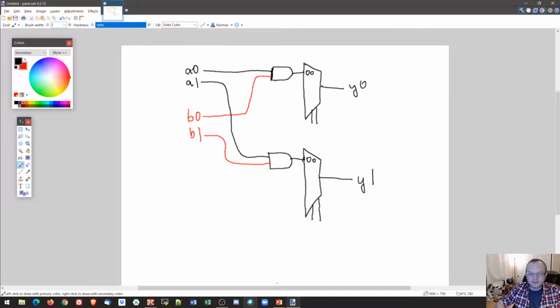So how do we control these multiplexers? Of course, if we want to choose operation AND, which is 0, 0 in selectors, then we want to have the same operation AND on both multiplexers. And the same for any other operation. We don't want to have a different operation on this multiplexer and some other operation on that multiplexer, right? We don't want that. So we have to connect selectors together because they will have exactly the same values respectively. So I'm connecting S1 to S1, S0 to S0, of the second multiplexer.